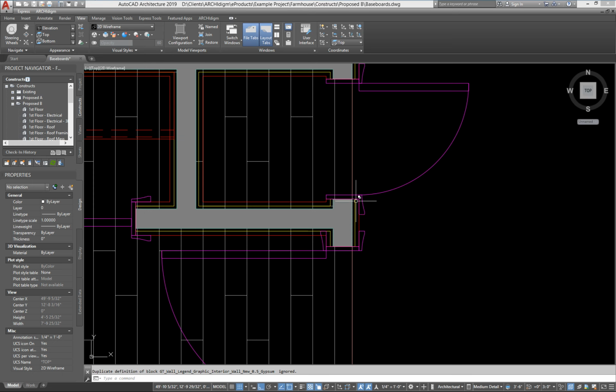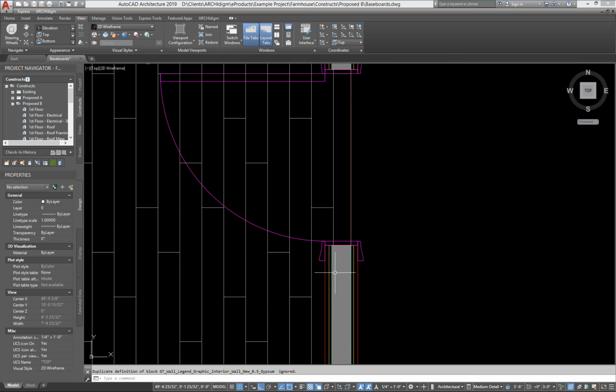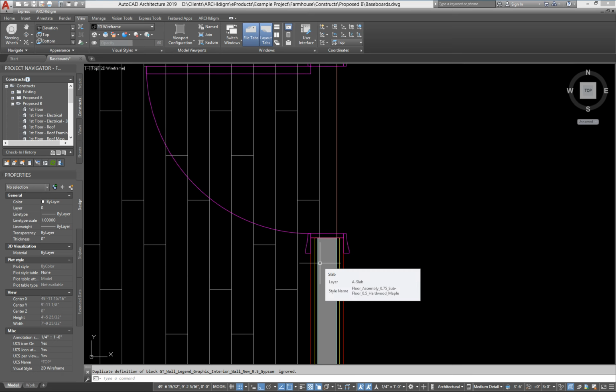All the doors had some kind of automatic adjustment. And the reason is that doors typically will read the width of the wall from the very bottom. So whatever starts at 0, they read that as the width of the wall and then automatically adjust. So you could compensate by working on all the doors, or we can do some little trick that I've discovered along the years of working with this software that I will show you right now.